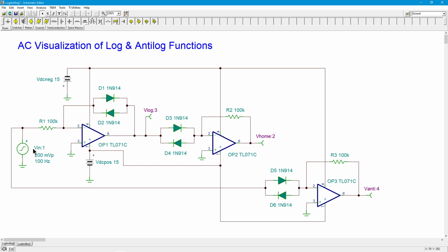Now, for those of you that are audioholics, this is a little bit different than when we talk about using an audio compressor. That's not what an audio compressor is doing. That's a variable gain amplifier, the gain of which is controlled by the overall average input level. As the input level changes, the gain changes, and we sort of limit, if you will, no pun intended, what the range of output is, right?